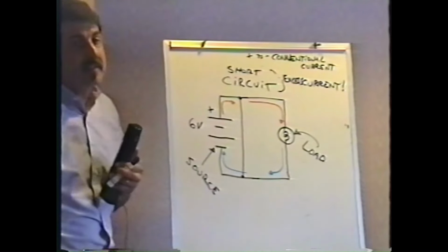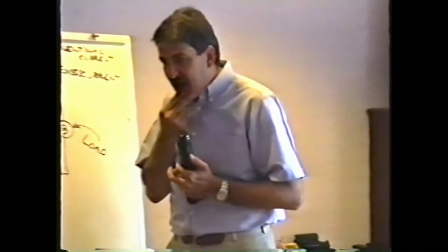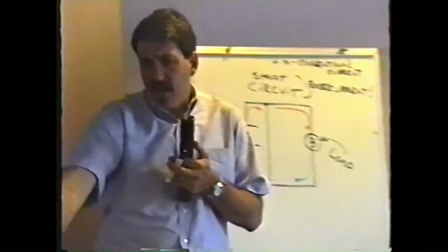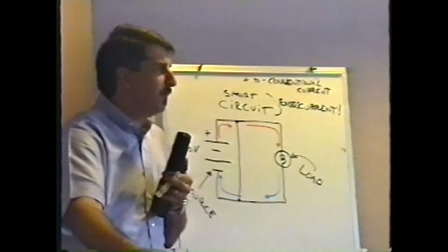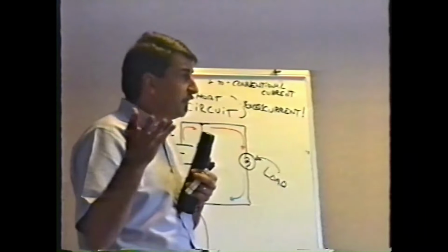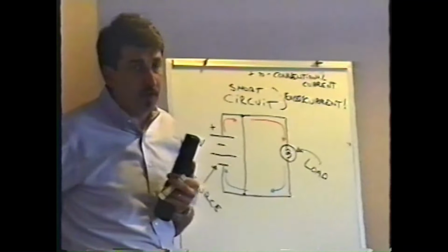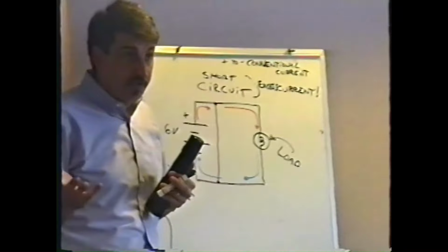The reason I point this out is that a lot of people just automatically assume that any failure they have is a short circuit. Like they equate short circuit with bad, like they mean the same thing. Like you go to a location and they'll be pointing to the pinball and they'll go, hey, that number 5 bonus light doesn't light up, it must have a short in it. Well, it's probably open, isn't it? The filament of the lamp is probably broken, it probably has an open circuit. So don't think that any failure is a short circuit.